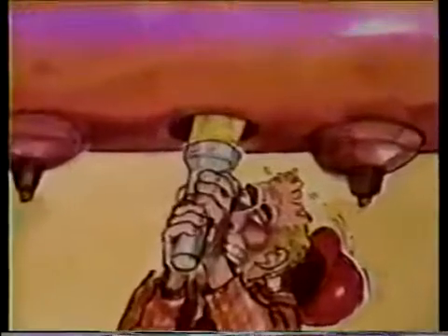Cracks often start in or near construction welds or places that have been repaired by welding. Both kinds of welds should be inspected for erosion and corrosion as well as cracks. You can't see every weld in the headers and tubes by looking into the headers. The tubes are too long for you to see inside surface details beyond the first few feet, if the tube is accessible at all. Usually the end of the tube won't be accessible. Tube access is limited by the amount of handholds in the header where the tubes are attached.